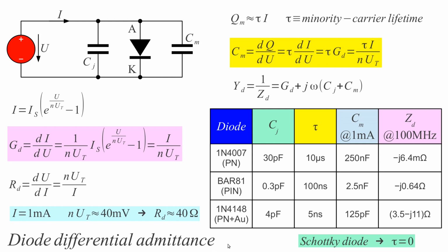What we should know also, besides all this discussion, is that Schottky diodes are really fast. In Schottky diodes we do not have minority carriers, nor do we usually use minority carriers in back diodes, though we can make them if we want in a back diode.